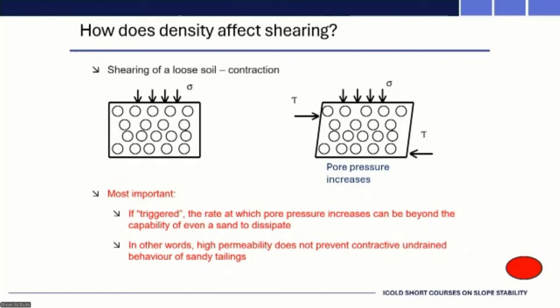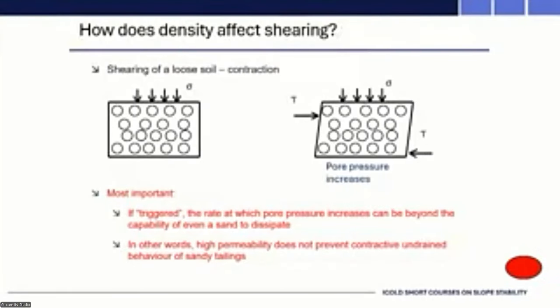You can be drained, it can push you further and further up in that stress path. Fourie was talking about a low K0 means you're closer and closer to this instability region. That whole process could be drained, but it's putting the material into a state such that it's highly susceptible to triggering into this undrained behavior. And once that happens, it might be a complete runaway.